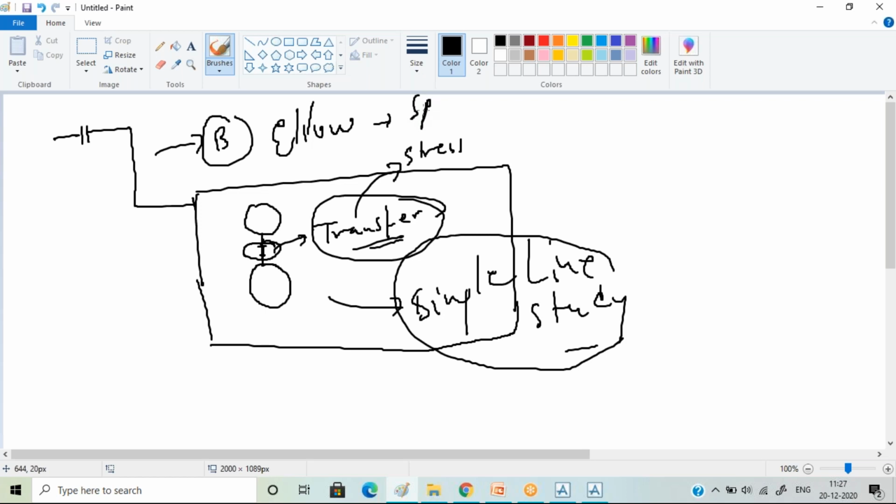It's very easy to keep on adding spools and elbows, but remember, the minimum amount of elbows has to be used. Why? Because elbows increase the cost of the project. So the minimum amount of elbows has to be used. This is what has to be considered in the piping. And the placement of the equipment has to be accurate, so that your spool is minimum, the number of elbows is minimum, and at the same time your stress is minimum.